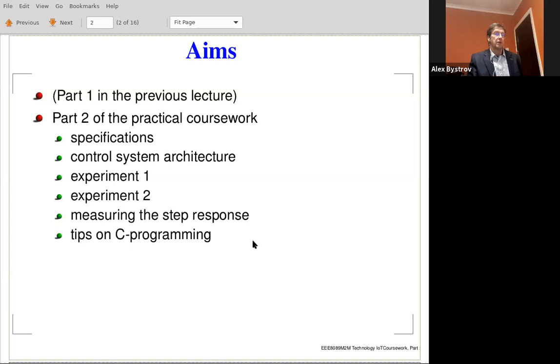Yes, the purpose of the PID controller, and any controller in fact, is to keep the error small and, at the same time, to keep the output roughly the same as the input with a minimum error. Without an integrator, it's quite difficult to have the output exactly matching the input.